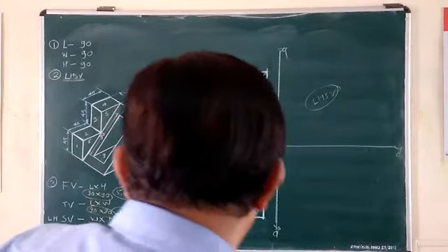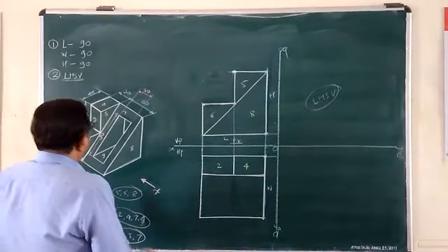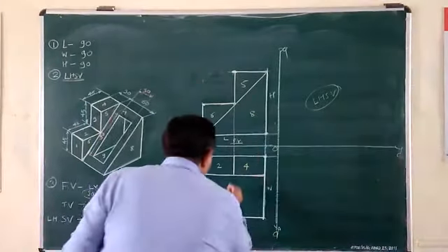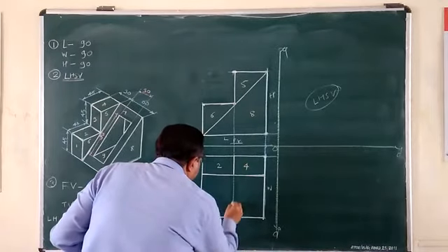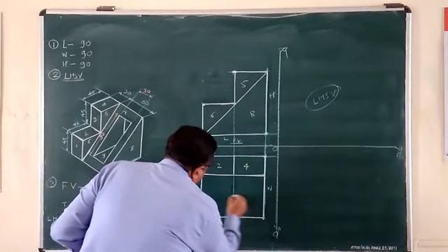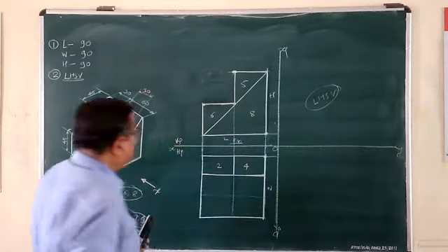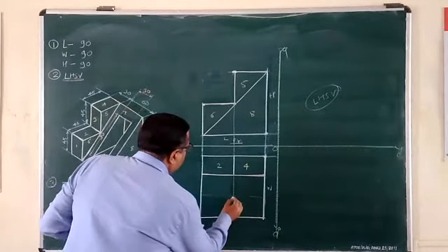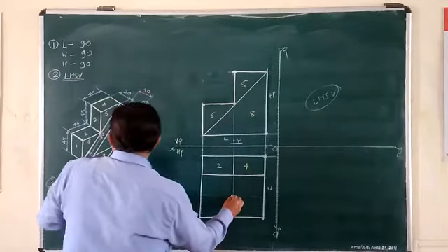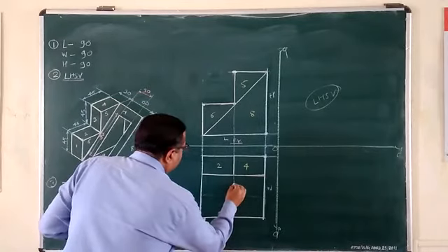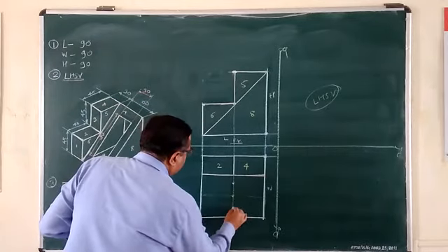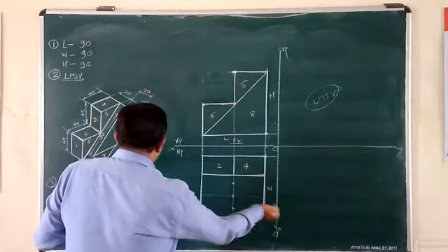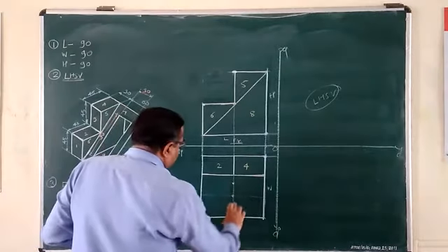Now what do you have to do now? These are the dimensions of that hole. So what do you have to do? Just draw center lines on this surface, vertically in this way. Paint center lines in this way. After that you mark that distance, particular size. How much is it? 30 by 90. So from the mid only you have to mark 30, means 15 up, 15 down, and 90. So 45 left, 45 right.